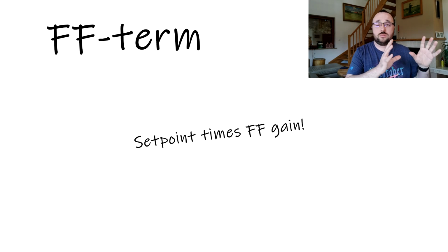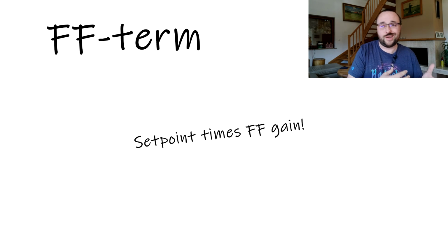So feed-forward works only and only with the set points, completely ignoring the measurements. In Betaflight, it acts like the accelerator of the movement, so that the response is not always swooshy and soft. If you really move the stick, then a derivative of the set point is treated as the feed-forward component. Complicated, never mind.